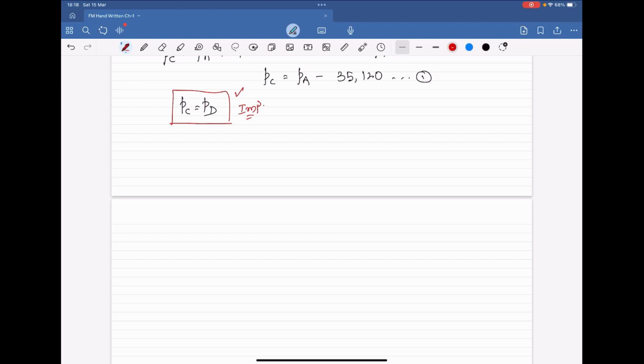As the system is static and under equilibrium, the pressure at C is equal to the pressure at D, because the medium is the same, that is air, and there are no obstructions in the connection. Please try to understand this concept also. I have taken this problem to clear the concepts for SSC JE and also GATE and UPSC aspirants. GATE and UPSC aspirants can try numericals like this, but SSC JE aspirants can understand the concepts.